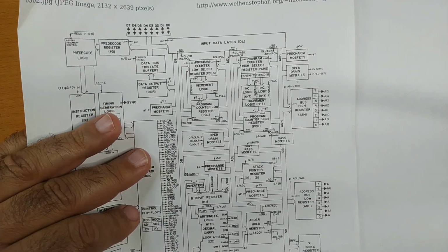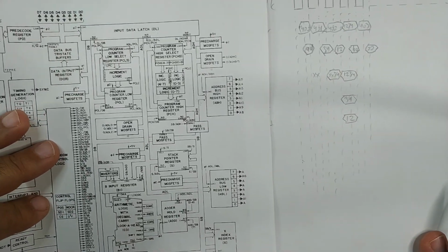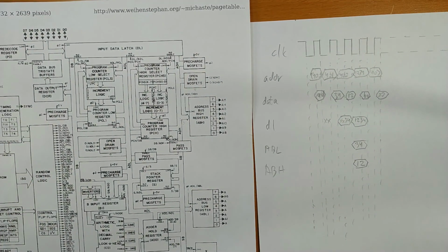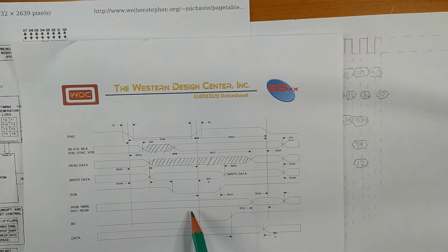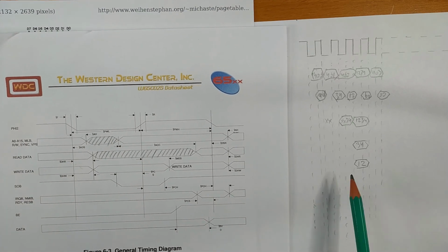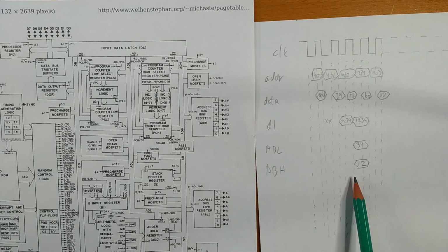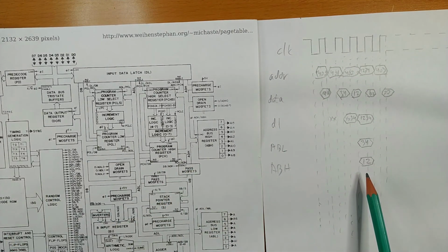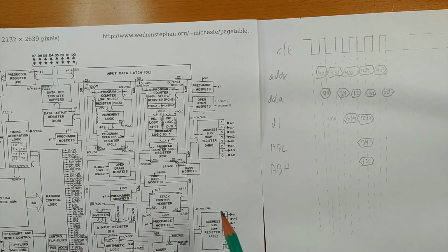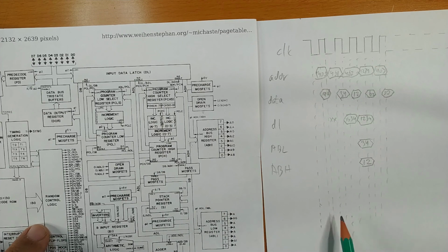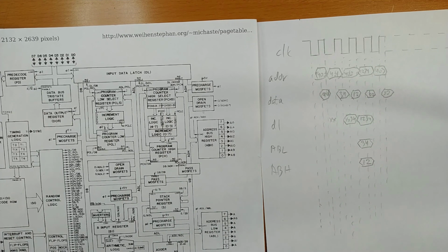Which shows you why timing diagrams are so important. They can teach you not only how to read them and understand the requirements, but also how to apply the requirements to your own design in order to see whether the design lives up to the requirements. And in our case, we've seen that we cannot both latch in the inputs and the outputs and be cycle accurate to the original 6502. But we can do all 3.